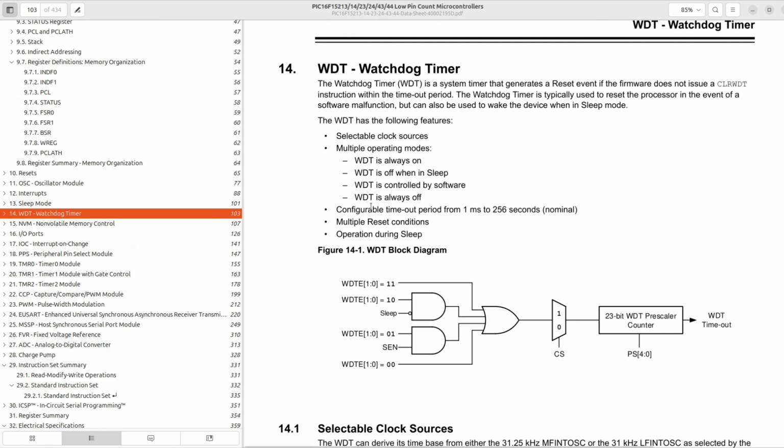What's happening here is that our device is actually resetting every 2 seconds. Why? Something called the Watchdog timer. This bad boy over here caused me a whole lot of headache. When I got started programming these devices, I spent days pulling my hair out over what was going on with this Watchdog timer. Although it was an incredible pain for me, this Watchdog timer is incredibly useful.